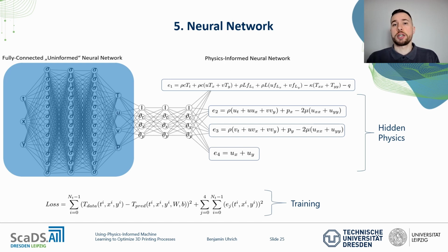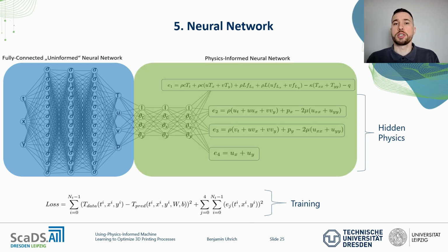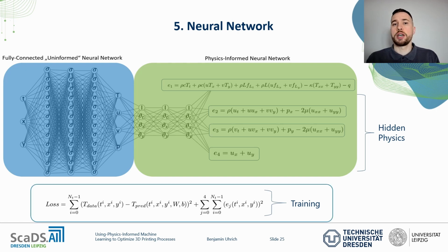Again, these learned functions are derived using automatic differentiation and inserted into the energy conservation equation and the popular Navier-Stokes equations. The idea is to learn the velocity fields and pressure fields only from the observations about the temperature profile and the differential equation relations. It is required to map the temperature distribution as well as possible while satisfying the differential equations.